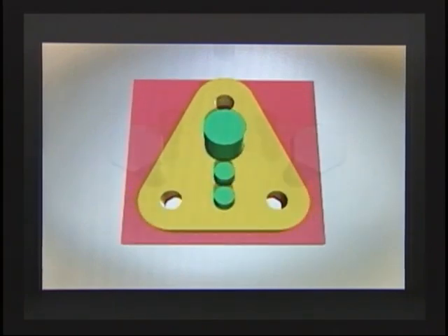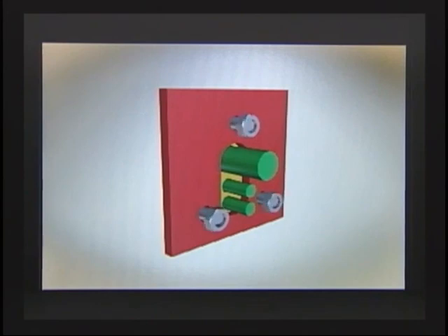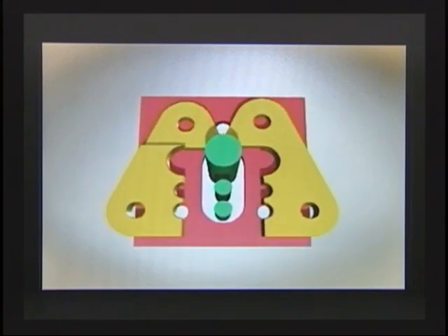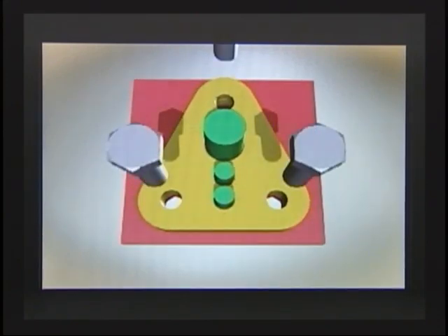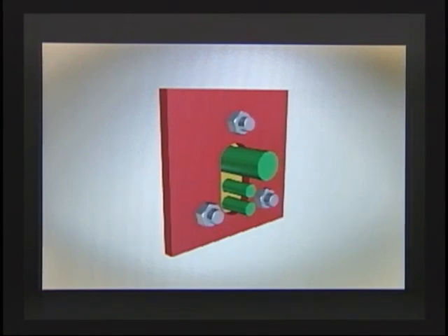And here the parts are going to come together. You see I'm going to put the bolts in. You see they're going to come around. I put the bolts through on the back side and we tighten up the nuts. Let me just show you that one more time so you can see it. There are the two pieces coming together. They seal around the cables. We're going to put the bolts through, the 3/8 bolts, put the nut on, and that's our assembly.